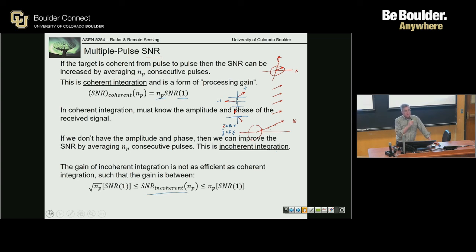I was just saying, if you had a forecast model of the target, you could just maybe rotate, because you'd know that it was supposed to be at a certain point, and you're keeping track of its phase. But you're saying that you might not know that until you've done the whole problem and you know the target's velocity and position and stuff like that. Yes. Okay. So if you didn't know this change in position with time, you would take the FFT, and that would fall into one velocity bin.